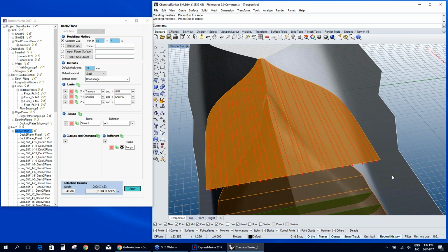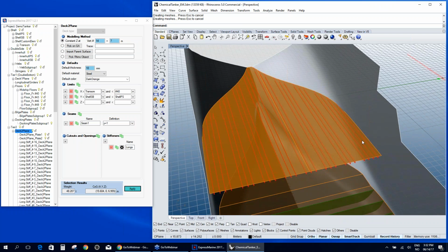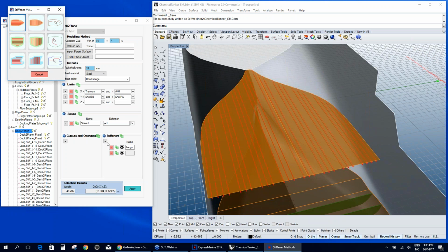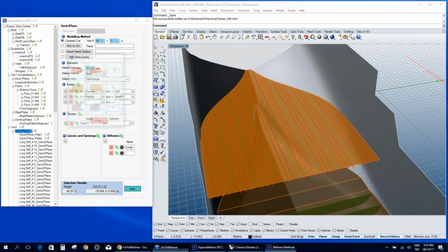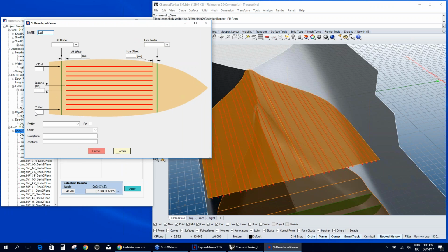And as you can see, the stiffeners have been created under the deck, and we have some blank spaces where we will further create the longitudinal beams. So we use again the plus button, and we will add again some longitudinals. This time we could call them LW, longitudinal webs, let's say. And we will define them in the same position where we defined the exceptions for the previous definition. So that would be from frame -12 up to frame 12, every 4 frame spaces.